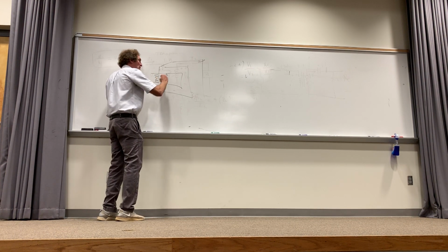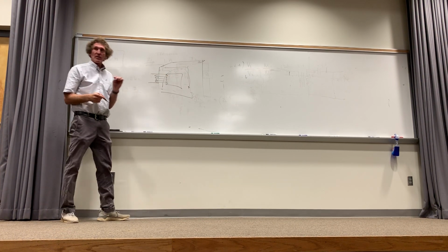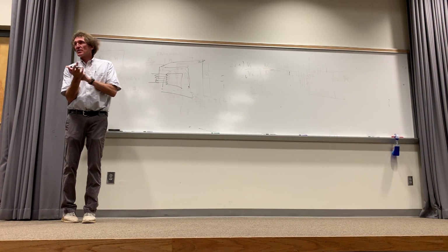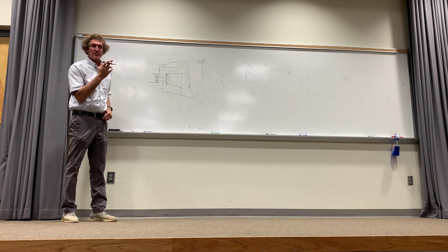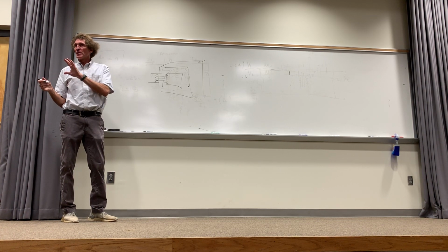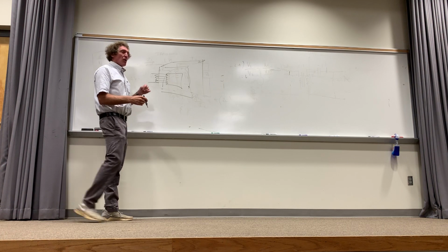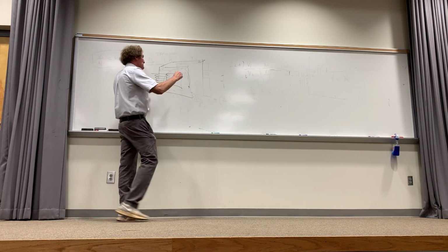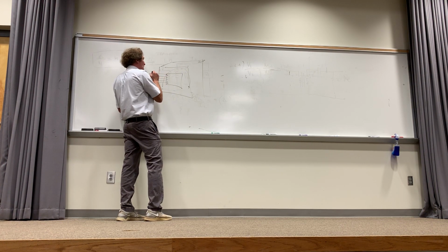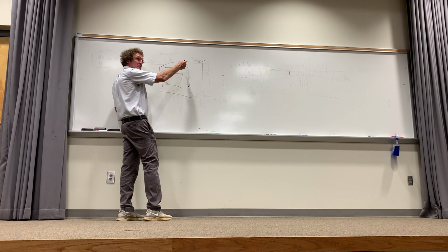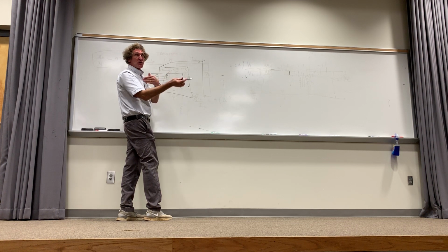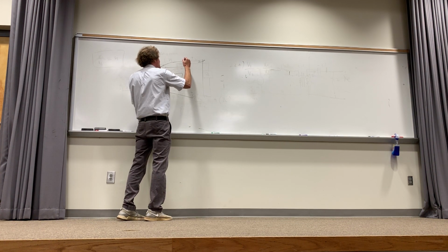Now, all the magnetic flux, if you remember physics, is going to be located within that. It's a laminated iron core. Laminations stop losses from something called eddy currents. That's beyond the scope of this course, but just appreciate that. Now, I need 240 volts. So now I take a winding, and if there were N turns here, and this is 7,200, then they're going to be less by the ratio of, say, 480 by 7,200. If there were N turns here, there's going to be a ratio less on turns here. And then I'm going to have one set of coils here.